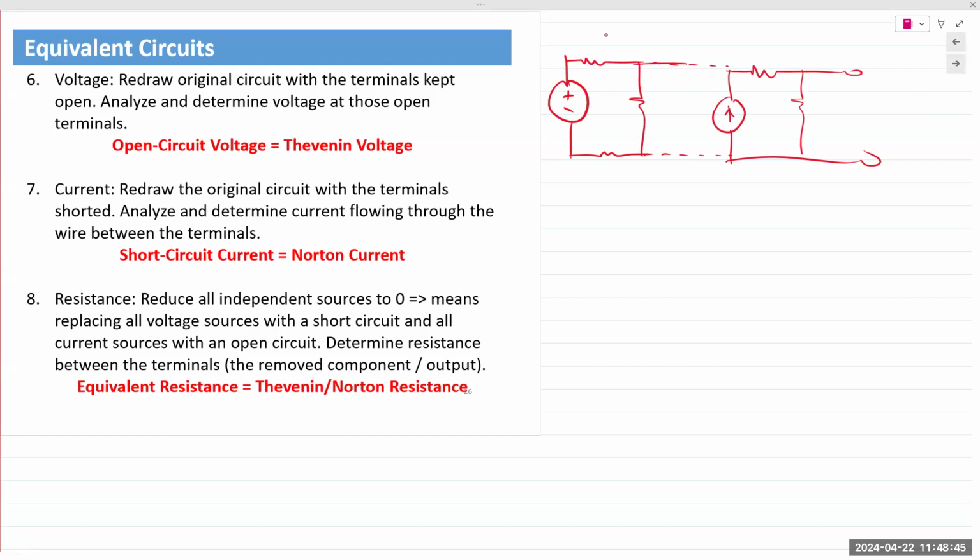Now, first, you have to establish your terminals of analysis. If it states terminals A and B, terminals X and Y, then you jump in right away. If there's a component connected to it, then you remove it. You have your terminals A and B. At this point, you don't do anything to the circuit. You simply apply your analysis technique and you find the open circuit voltage with the polarity shown. The resulting voltage could be positive, could be negative. That doesn't really mean that your answer is incorrect, right? But you analyze with the polarity that is shown here between terminals A and B.